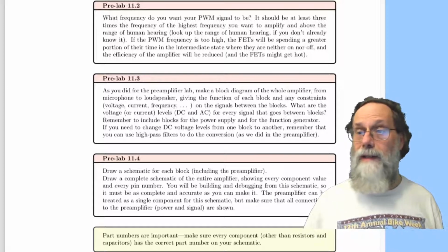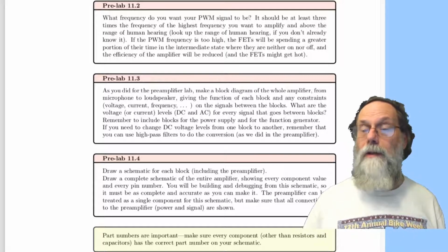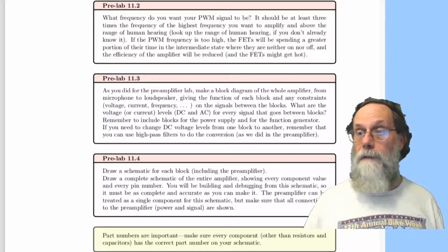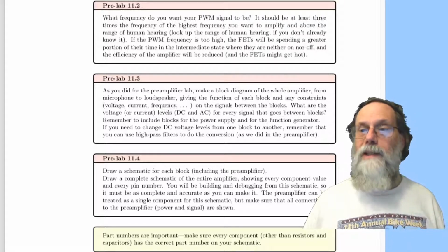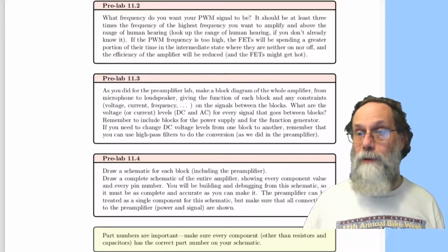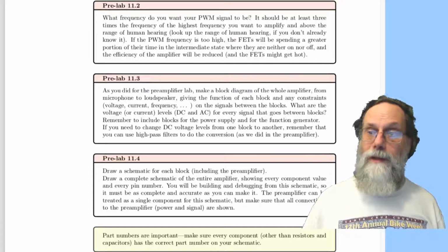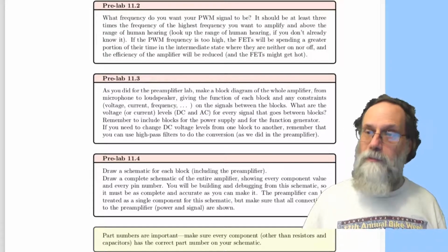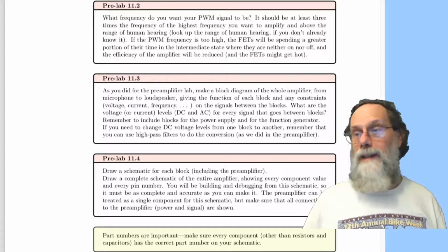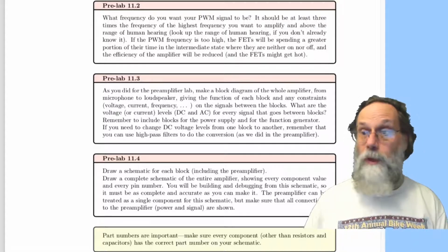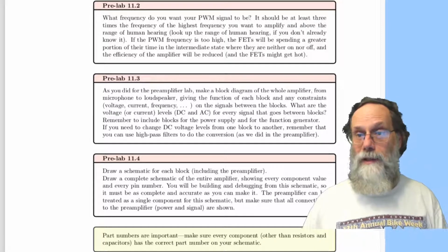And again, there's not a correct answer here. This is a design problem. There are trade-offs. Make a case for the PWM frequency you choose. Make sure that it's consistent with the frequencies you're planning to amplify, and that your transistors will switch at the frequencies you've requested.